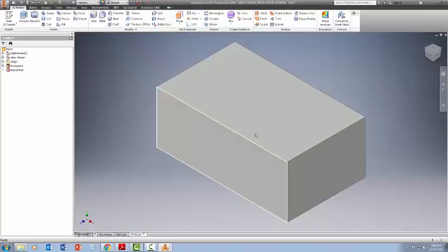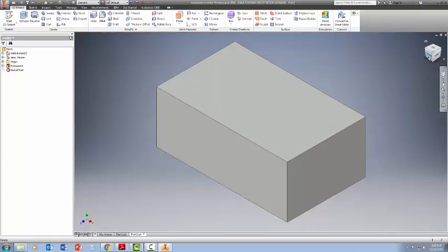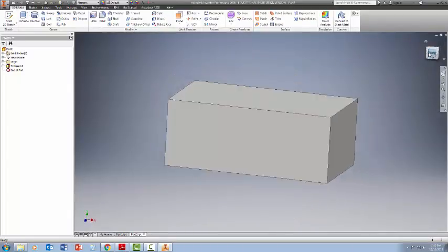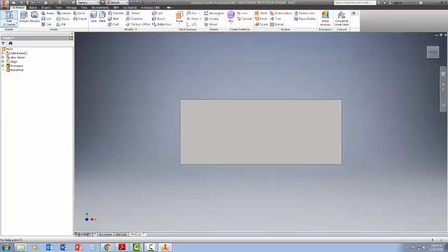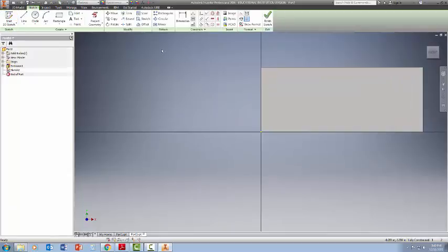So we're on here. I'm going to click Front View on the right hand side. Start Sketch. Line. Click. This was 2 inches. Enter. I bring it down 90 degrees, 1 inch. Enter.